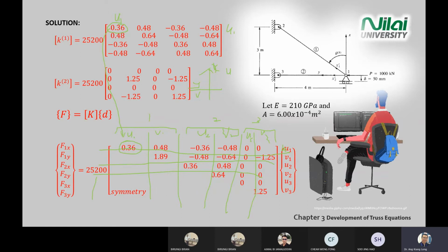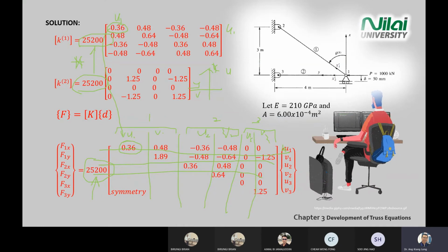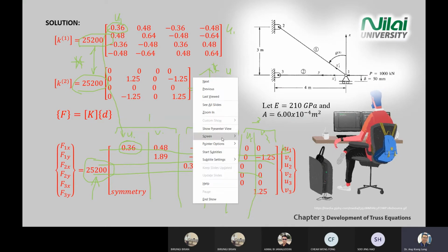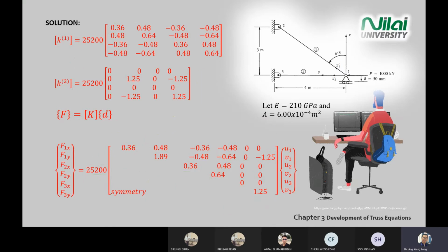All right. As you can see, when you write F equal to KD, the constant value will be the same for matrix 1 and 2. Both are showing 250 and 250. This is the area where 1 or 2 students will forget. This is the area that you need to be careful with before you do the superimpose. Before you park the number, make sure the constant value outside the bracket here is the same. And then you repeat the same like what you learned in chapter 2.